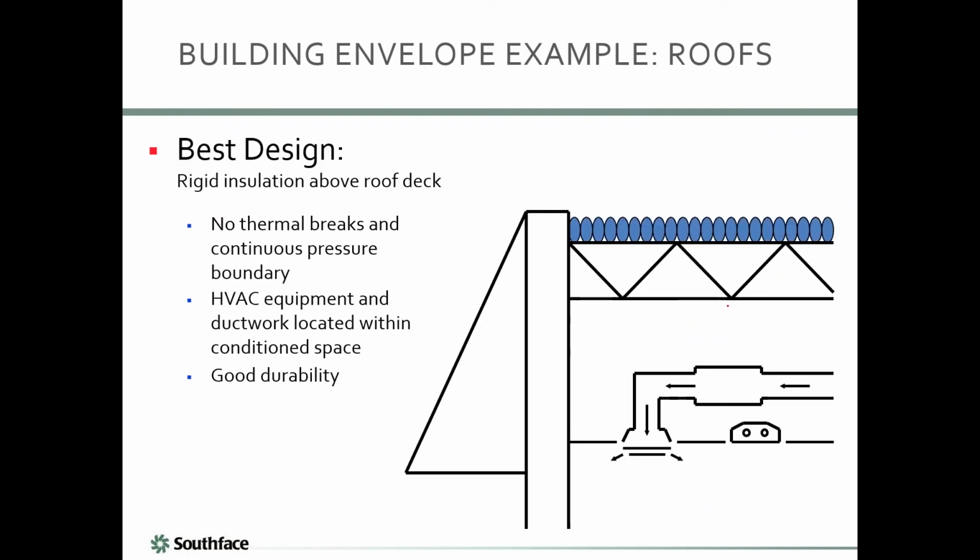Where's the best place for roof insulation? Continuous above the roof deck. No question about it. It's not broken up. It's airtight. It's got a good track record. And if you have your ductwork or air handlers, at least now, it's obviously 100% inside.